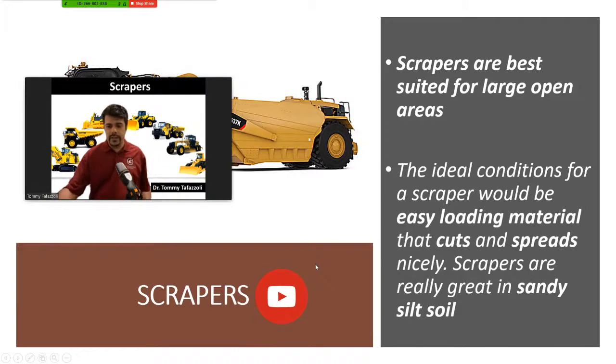Okay, the ideal condition for a scraper is soft materials. As you saw in the video, the material was very soft. So they cannot work well on rock and hard materials. So easy loading materials and sandy, for example, sandy silt soil would be an ideal option for scrapers.